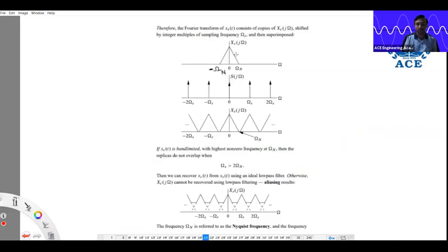Suppose we are assuming the reference spectrum as a triangle. The impulse train spectrum is another impulse train, that we know. The reference spectrum is a band limited spectrum like this, sir. If we are assuming the band limited spectrum as omega m, there I used the omega m symbol in our derivation. The impulse train spectrum is an impulse train. We observed whether the oversampled spectrum is valid or not. To avoid aliasing, omega s must be greater than or equal to 2 times omega m.